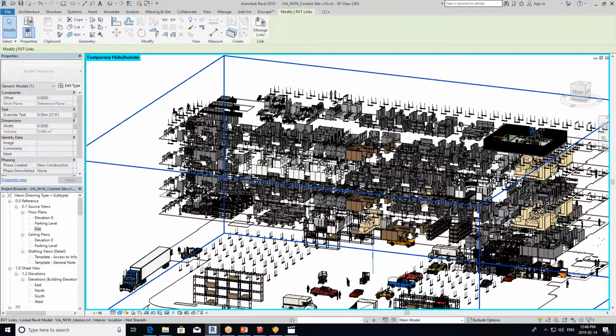Yes. I would use Lumion if your client wants a rendering and the design is finalized, you don't change anything. I would use Enscape only if your design is still ongoing and you have a consultant that keeps sending you files. Then Enscape is much easier to set up. But both have their place. One will do animation, this one would not. Just keep in mind, if you have a closed door, it's a closed door unless you model the door to be slightly open and you walk in.